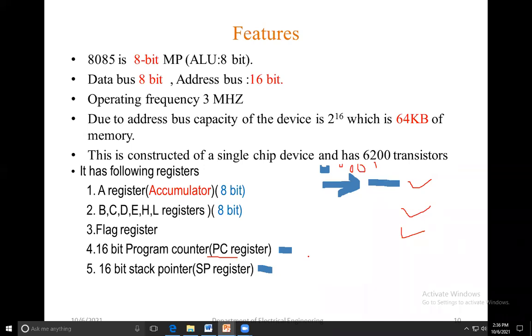Okay, so when you're programming, in the last lecture we discussed the Keil software. We have to execute the instructions step by step. You have to use F11 for stepping through instructions. So this is a program, and this is a stack pointer. This stack pointer is used.